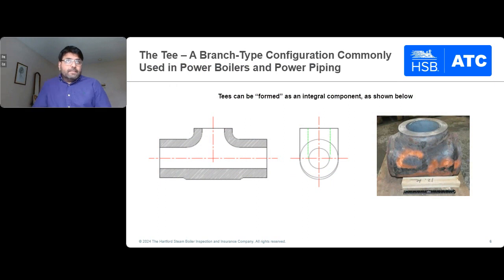So, as I said, under the rubric of T intersections, you can have 2-3 different combinations that are commonly used in the boiler system. This sketch that I have here is an example of a B16.9 T. I want you to pay attention to this run extension beyond this tangent line from the crotch. I also wanted to point out the branch length here.